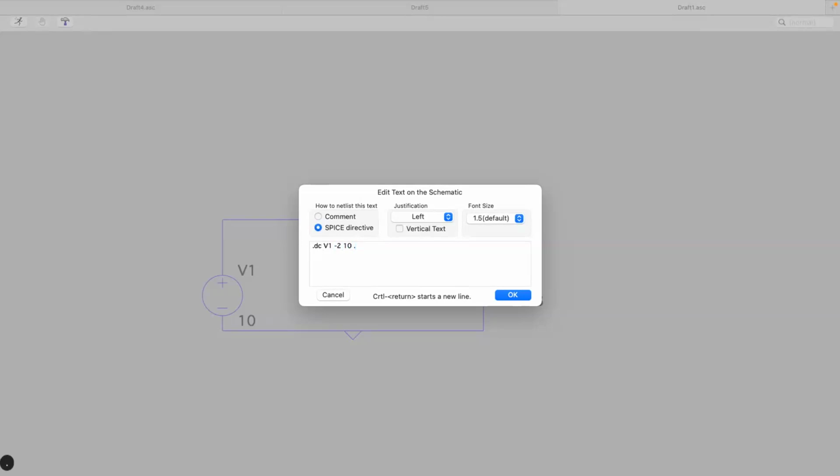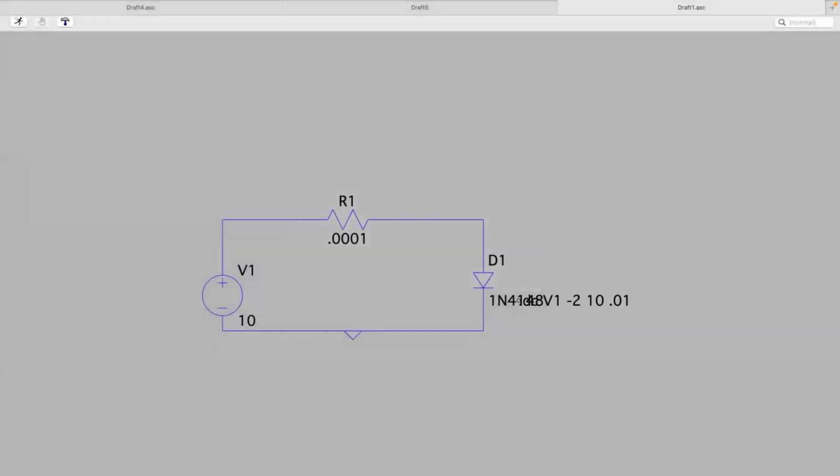If you choose 0.01, then per volt you'll have the inverse of that many steps, so 100 steps. If you choose 1, it'll just give you 1 step per volt and your graph will look kind of funky. So I'll go ahead and put that in there.